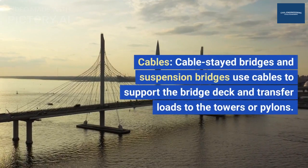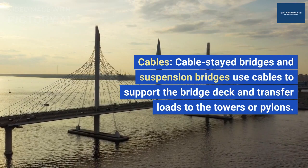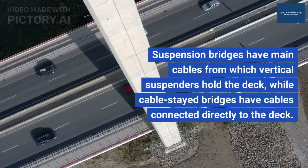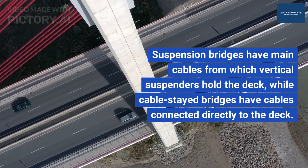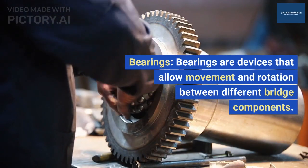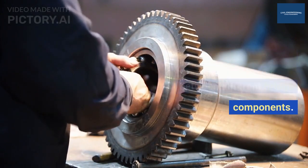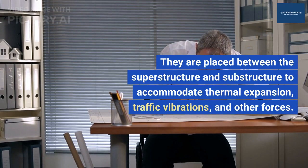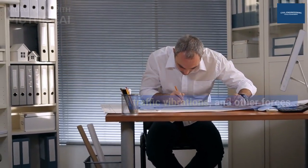Cables. Cable-stayed bridges and suspension bridges use cables to support the bridge deck and transfer loads to the towers or pylons. Suspension bridges have main cables from which vertical suspenders hold the deck, while cable-stayed bridges have cables connected directly to the deck. Bearings. Bearings are devices that allow movement and rotation between different bridge components. They are placed between the superstructure and substructure to accommodate thermal expansion, traffic vibrations, and other forces.